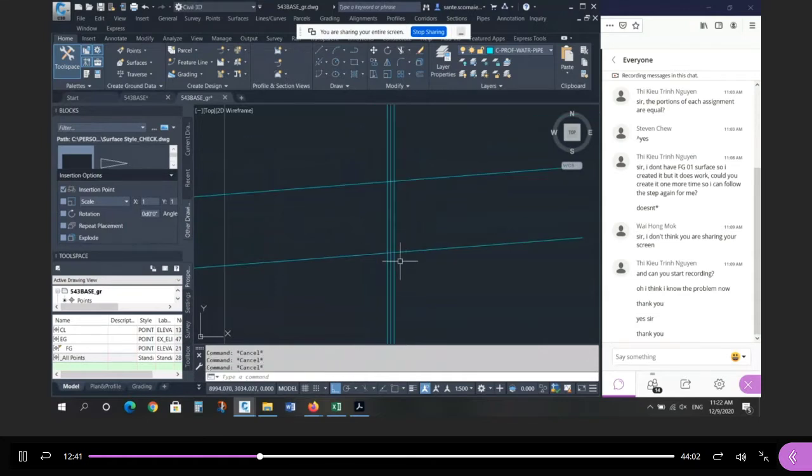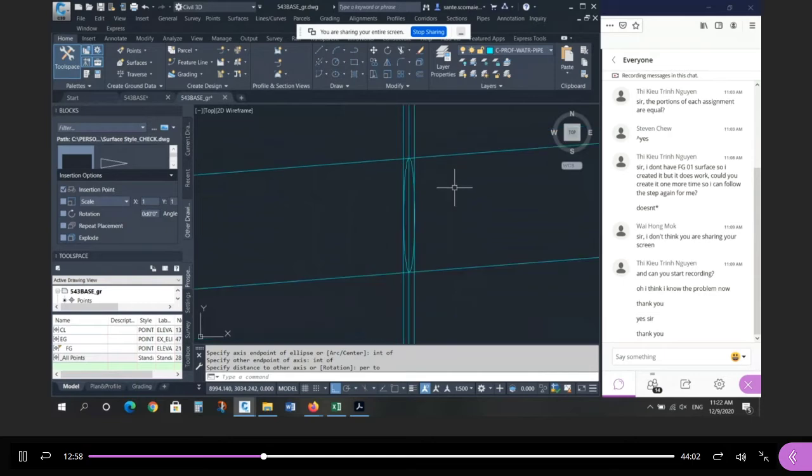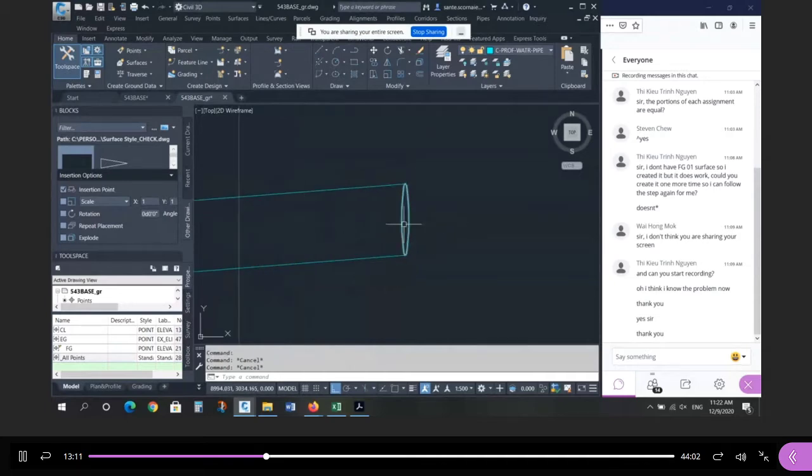And then here we can use an ellipse. So this is the center, right, the end of the pipe here. So I'm going to draw an ellipse, which is a circle stretched vertically. So I'm going to go from the intersection here to the intersection here, perpendicular to the width, and that's what it would look like in profile. So now I can get rid of all these construction lines and trim it here. And if you want, you could even trim it here. Right? But I like to leave it because here you would actually be looking at the cross section.